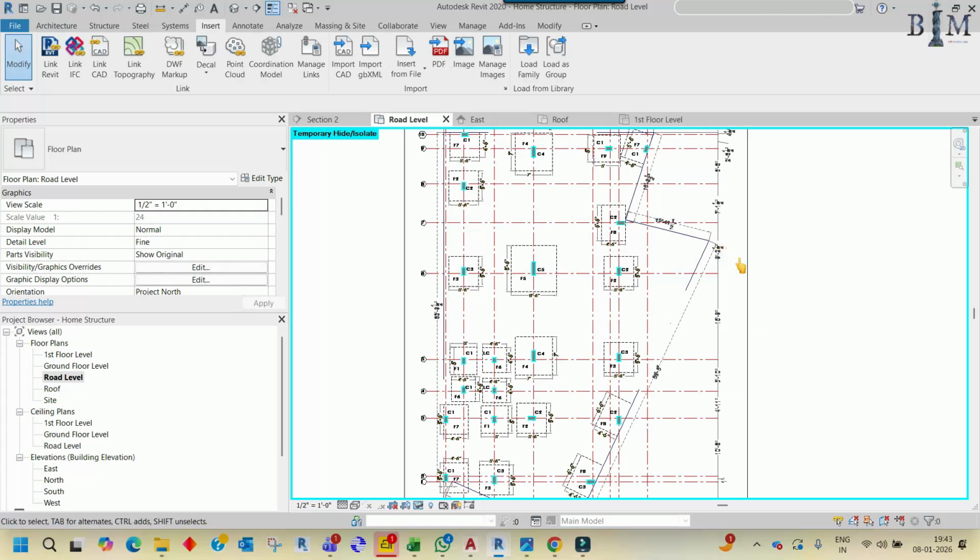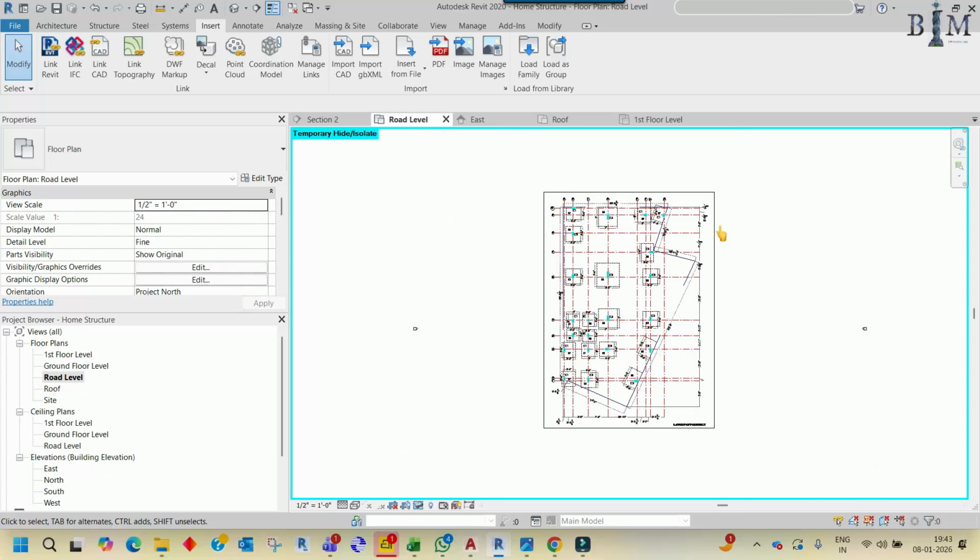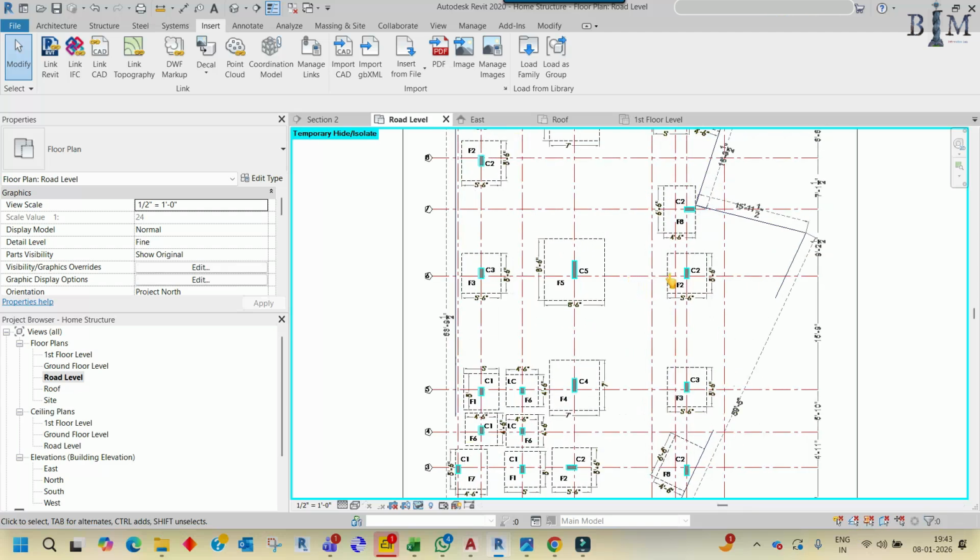If you want to turn off the snap, in that case as this is a pinned element, take the pin, and here you cannot snap it, so it is an object but you cannot select it. And if you take this attach, this attach means you cannot select any attached element. So now these all options should be crossed, means they should be turned off, because for safety purposes maybe in that case your model can move anywhere. So to prevent this, you have to take them all first, and now your model is ready.